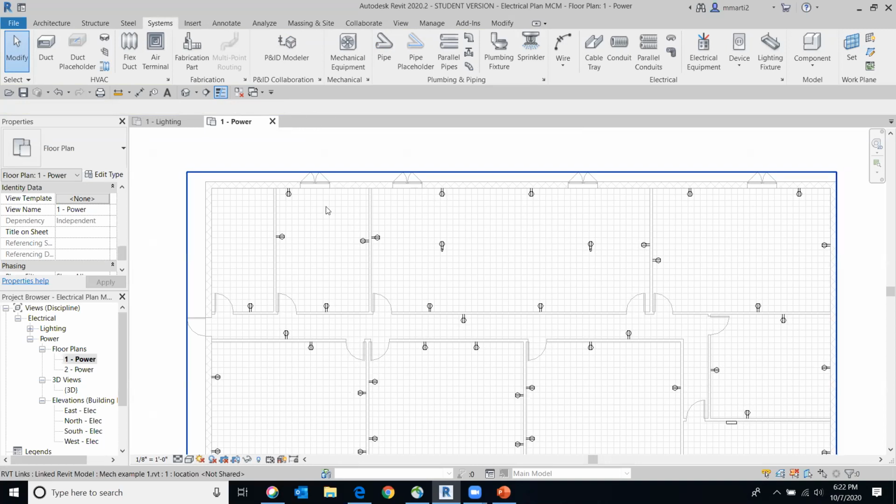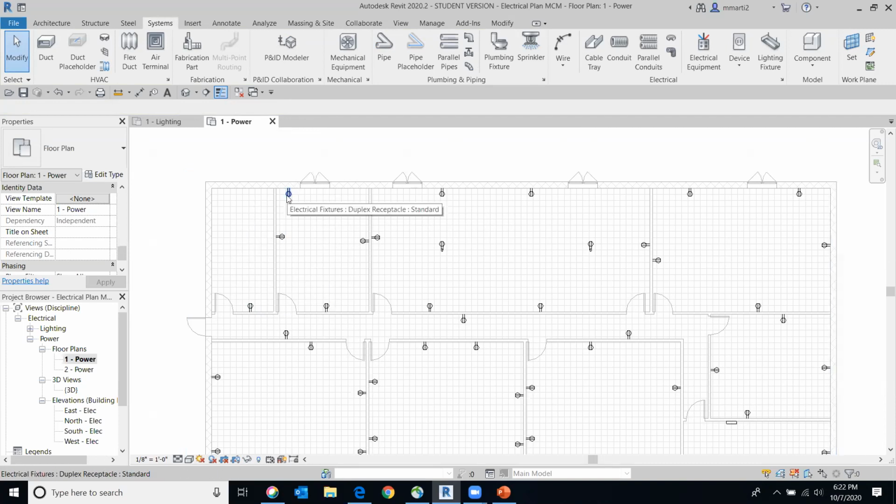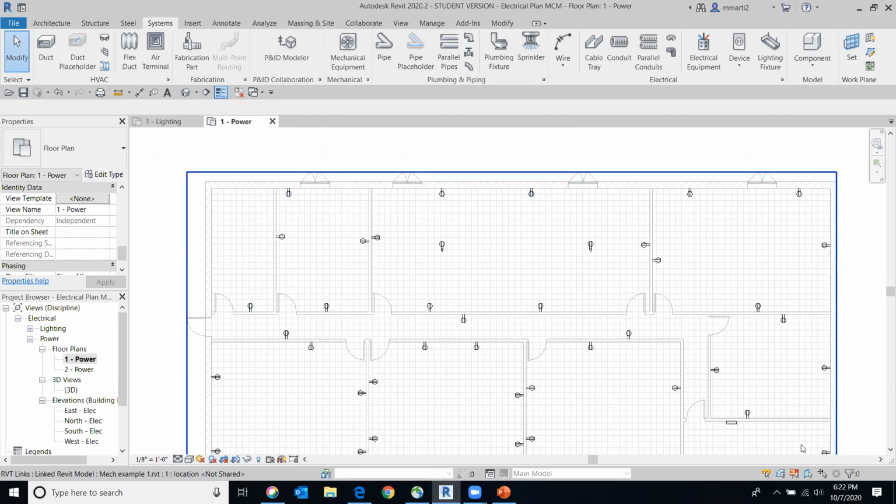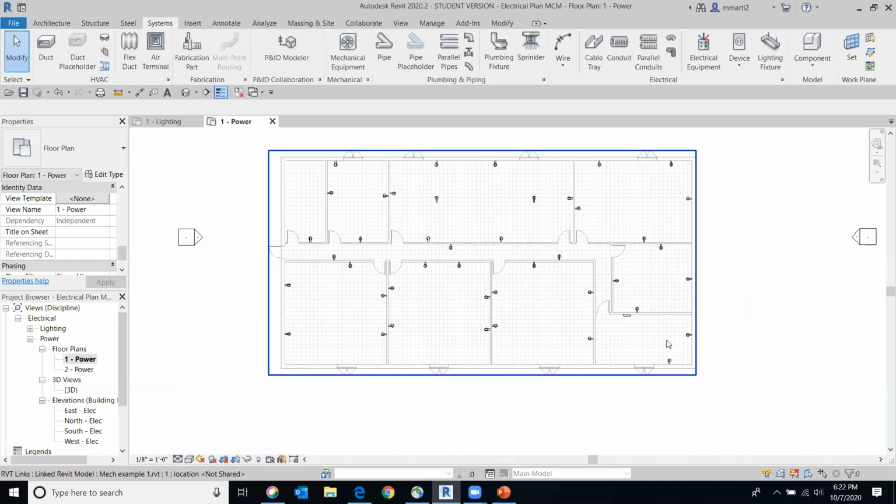So you want to think about how they're organized. So typically what I do is I do that by room and area. So I know that all of these will be on the same circuit line. I wouldn't go like this one and then this one and then one over here and arbitrarily just pick outlets. Once again, think about the method you want to do something in order to connect these to that one circuit line that will come back to this panel board.